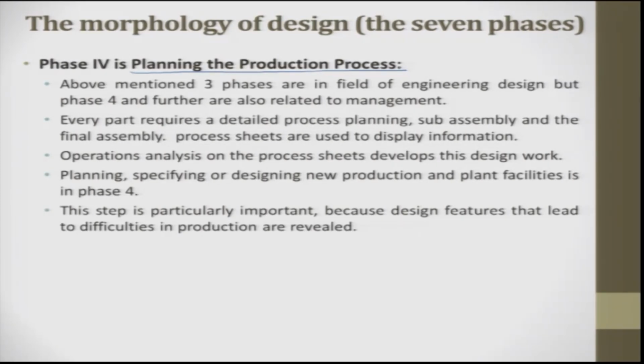Very difficult, you can't make a process. And if the detailed design says a square shaft has to be made, it is pretty difficult for a long one. If you want to do extrusion, possible, but again in extrusion also square edges is very difficult. So, people always try to go back and say, no, it is not possible. Can you convert this square into a circular one?